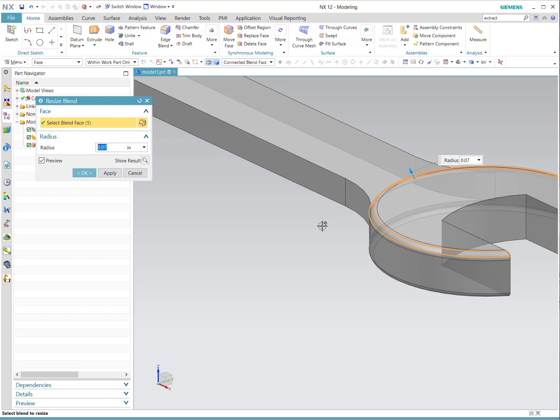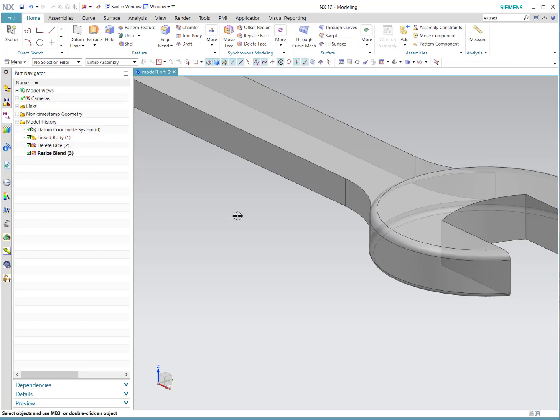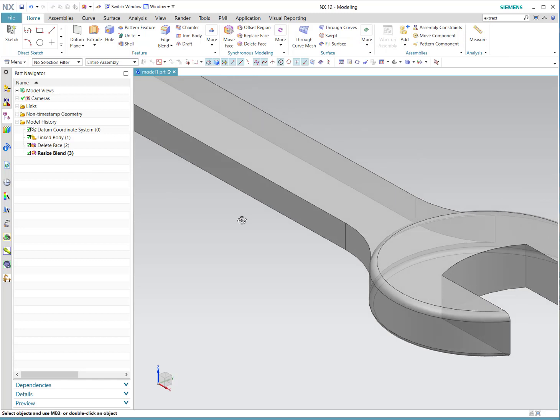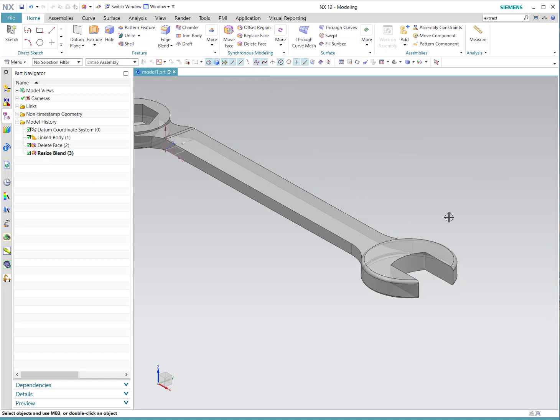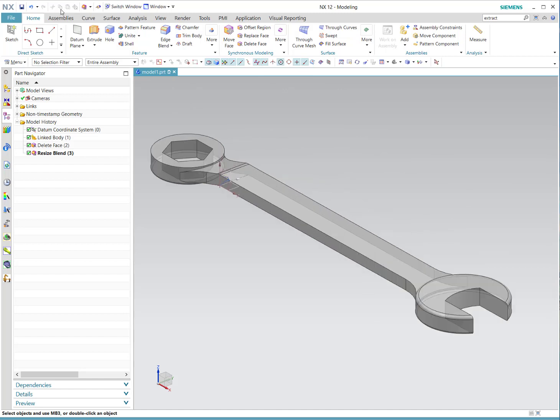On an internal radius, sometimes it's nicer to have a ball mill that's a little bit smaller than the radius in a corner, or maybe if it's a plastic mold, from your knowledge of mold making, if that radius is a little bit within part specs, of course. So you can make modifications to that model on top of the original design component.